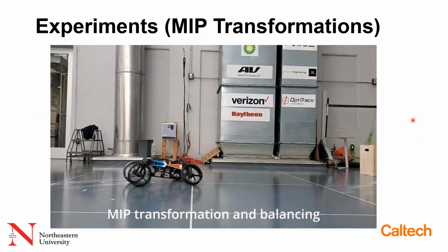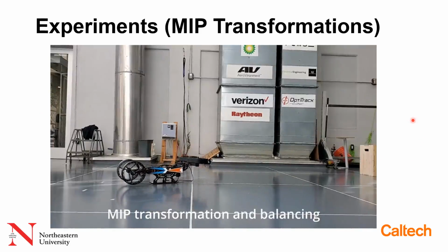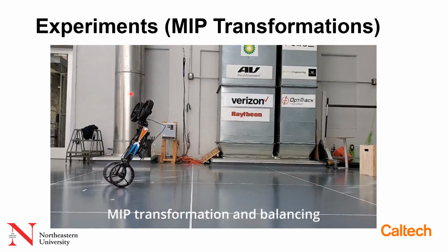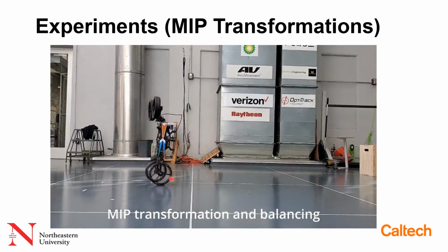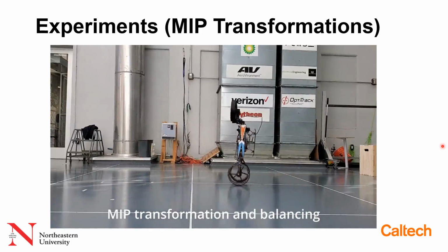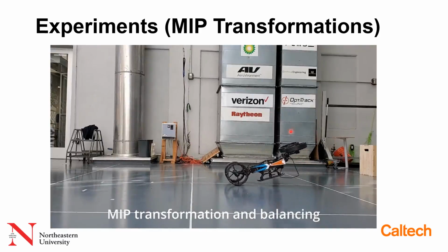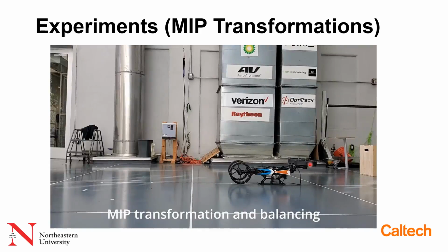This slide shows how the robot transforms from the rover mode into segway mode. The robot transforms into the correct configuration and then uses the thruster to lift the robot up, upright it into the upwards configuration, and then in here it will do the standard segway balancing with just the wheels. And if you want to transform back into the rover mode, you can do the reverse action by slowing down the descent using the thruster, and then transform into the rover mode after it has safely landed.